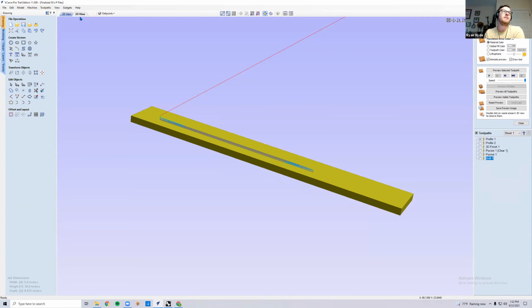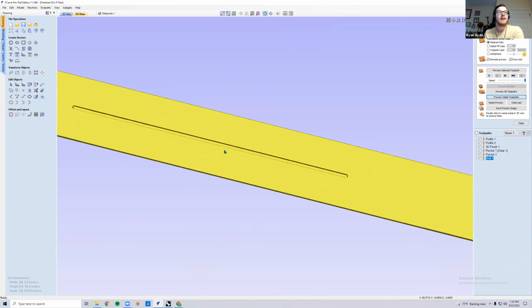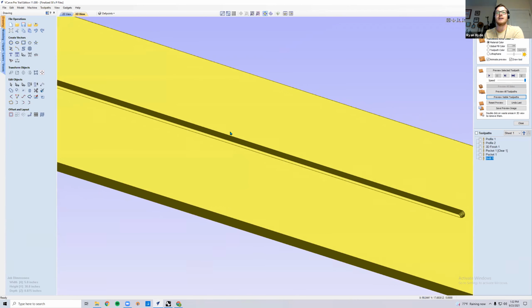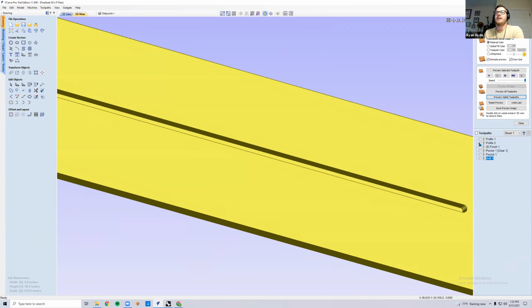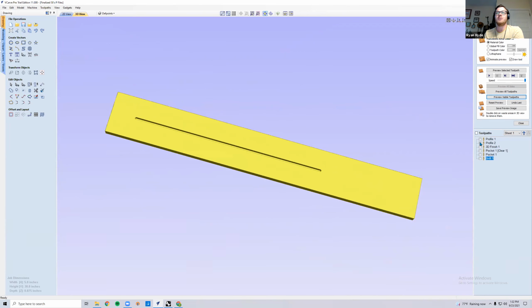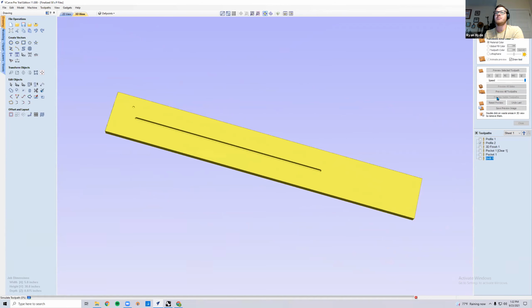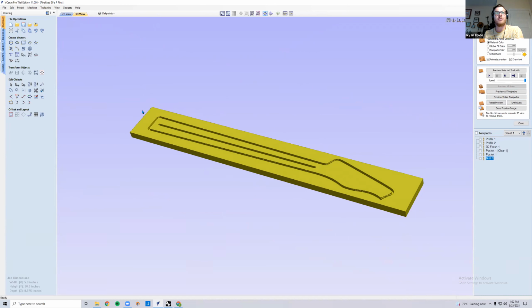It's the profile one. And if I say preview that visible toolpath, we're going to see what the CNC does, and boom, there's my truss rod slot. So I've had it mill this truss rod slot 3/8 of an inch deep to fit the truss rods that I know I'll be using. And if I zoom out a little bit and go to profile 2, there's a profile of my entire neck. So if I preview that guy, bada bing, there's our profile. So we're halfway there, folks.